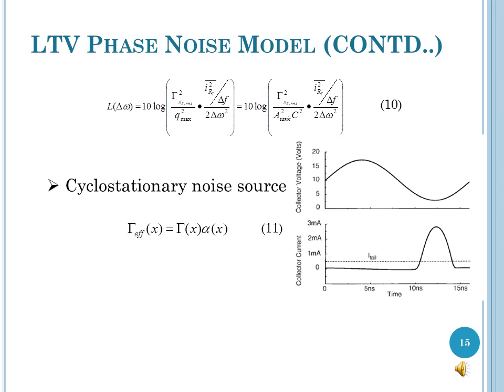The key concept demonstrated in ISF theory, or the impulse sensitivity function theory, was that the impact of the noise sources that are activated during the operation of a circuit varies across the oscillation period. In other words, the same noise source generates a different level of noise depending on when it is active. Hence, if the operation of the oscillator could be controlled such that it delivers energy during the insensitive instances in an oscillation cycle, then the phase noise could be minimized.